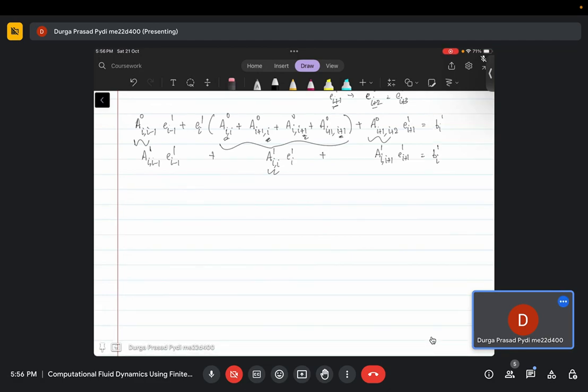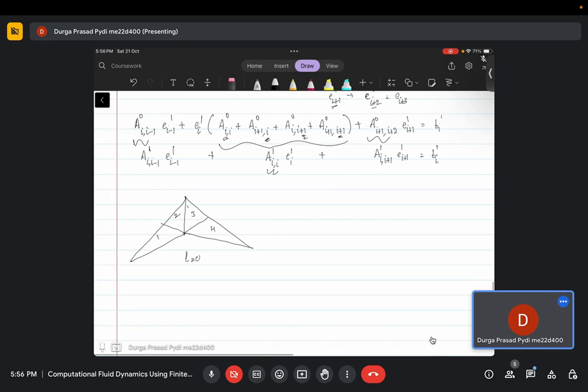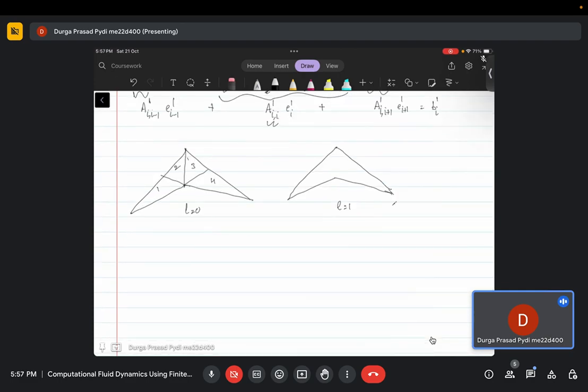So now that you brought it up, maybe say suppose you have something like this. So you have Dirichlet on all the boundaries. Some mesh like this, some unstructured mesh. This is say my level 0, and say my level 1 is, okay, maybe you should not take an element like this, but suppose this is my level 1. So you will essentially solve only one equation, so you don't need any iterations to solve in level 1.